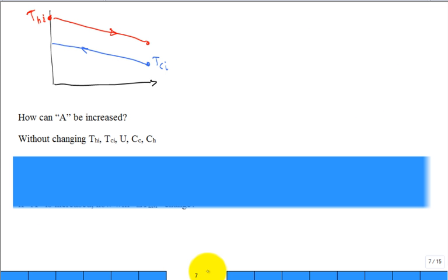All right. Well, after the explanation, I think you get it right. Let's press forward. This is a very simple question, not a clicker question. Here is the heat exchanger. How can I increase the area of my heat exchanger? How do I increase the area? Make it longer. It used to go from 0 to L. Here, 2L, 3L. You just stick it way out. That's the easy answer for how you increase the area.